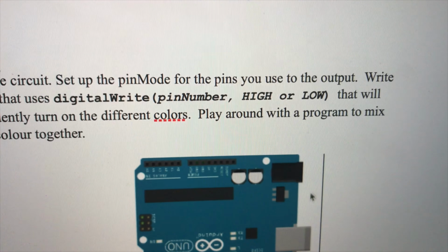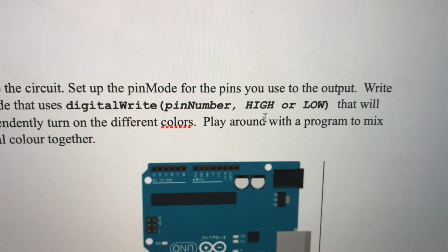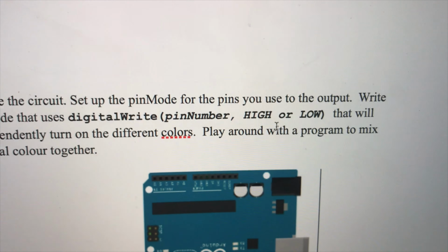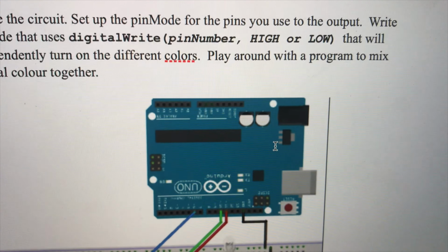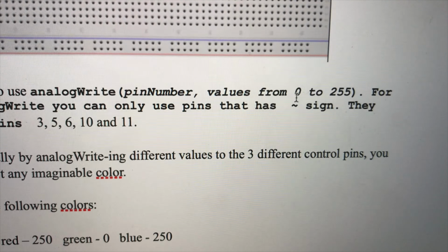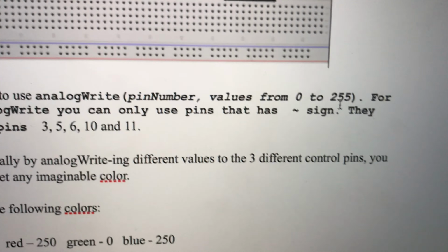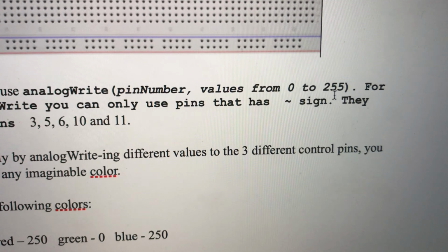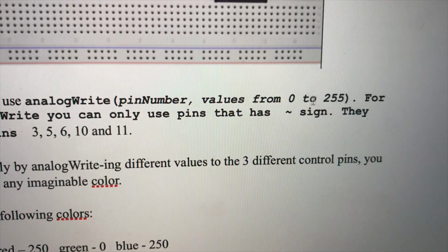You may be asking, why does it work like that? In the case of digital output, there are only really two options. It communicates in binary, which is just 1 or 0. Only those two values, which means you cannot go in between. It will only be completely on or completely off. But analog gives you the option to go to the middle, because it goes from 0, 1, 2, 3, 4, 5, 6, 7, 8, 9, 10, 11, all the way up to 255, which means you can explore middle values like 174 or 190. So you can play with those middle options, and it doesn't have to be completely on or completely off. It can be in the middle as well.